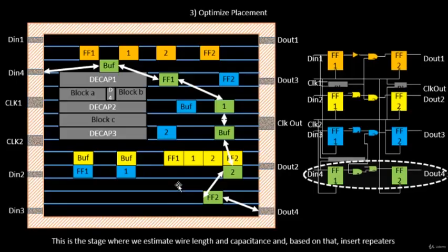A setup timing analysis, and not hold, basically. Hold will not make any sense once we don't have the clock. So let's try to do a quick setup timing analysis with ideal clocks. Based on the numbers that we get out of the setup timing analysis, we will come to know whether the placement that we have done is reasonable.